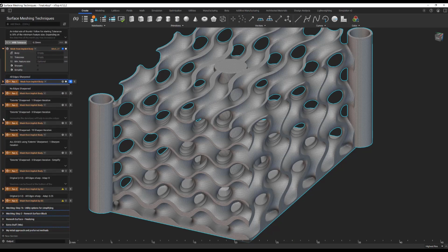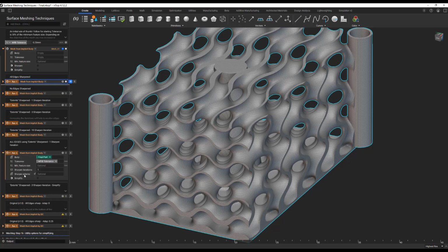If you do want to try and sharpen all edges, I still encourage you to access the overload. You can leave the sharpen extents blank, in which case it'll work to sharpen all edges, but now you can control the number of iterations that you want to work with.